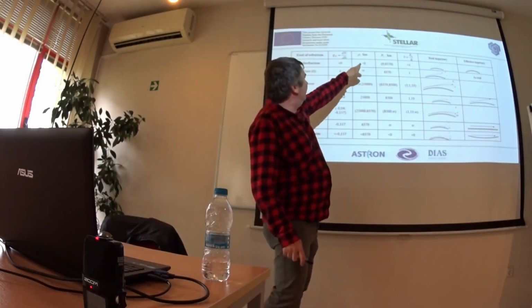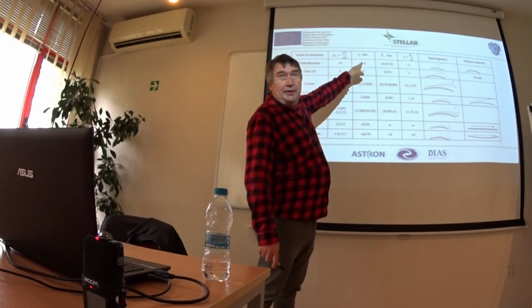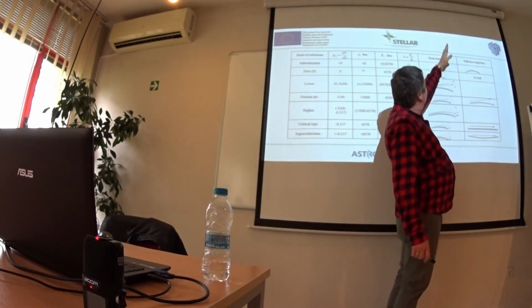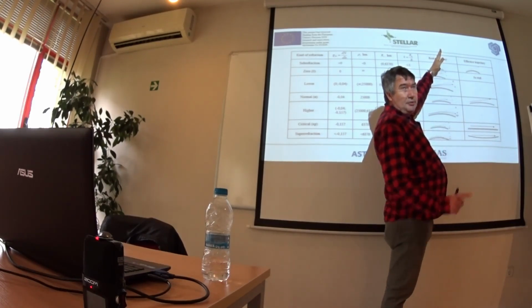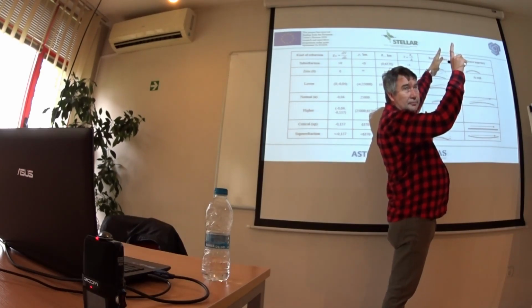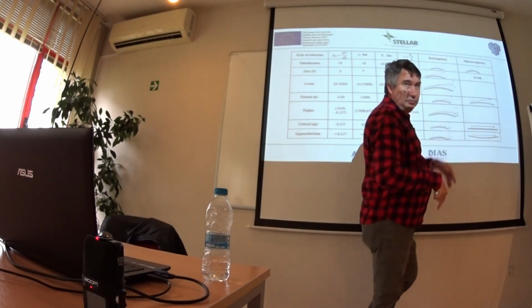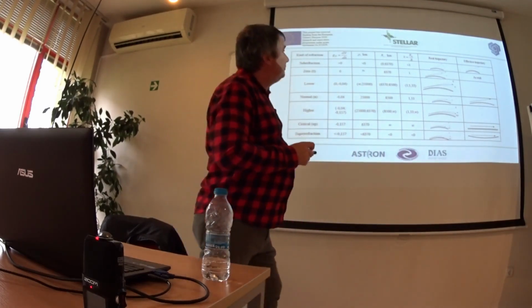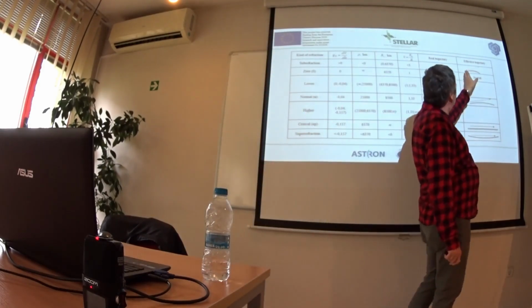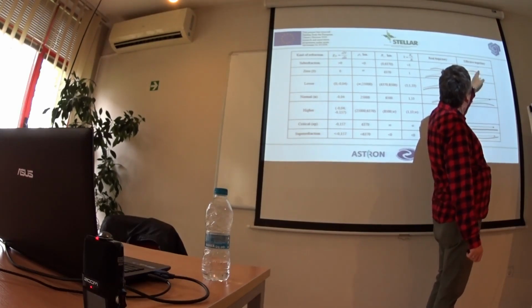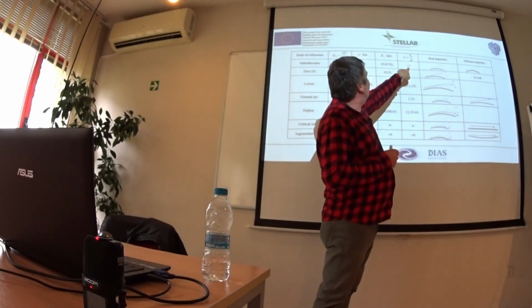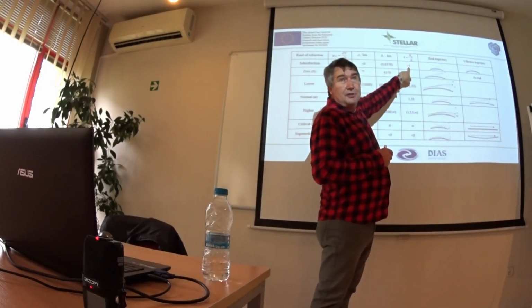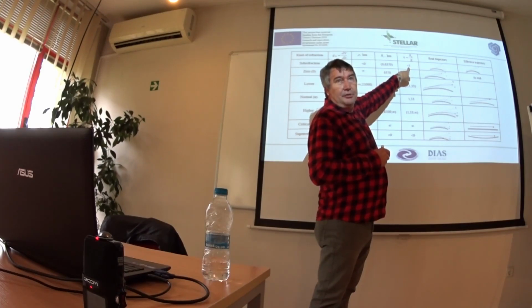In this case, the path radius is negative, or this is the wave path. It bends to the space, not to the Earth. And in this case, the effective radius is smaller than the real radius of the Earth.